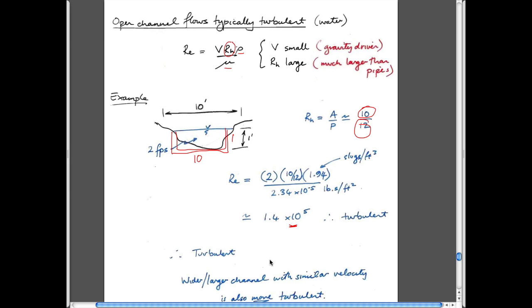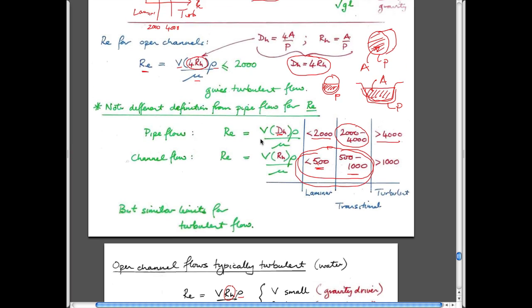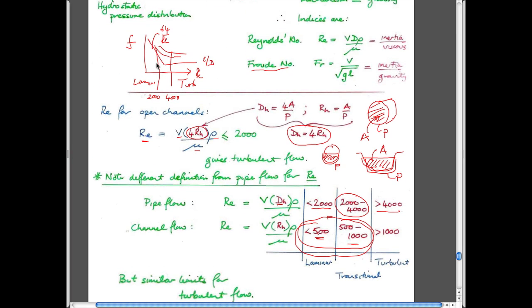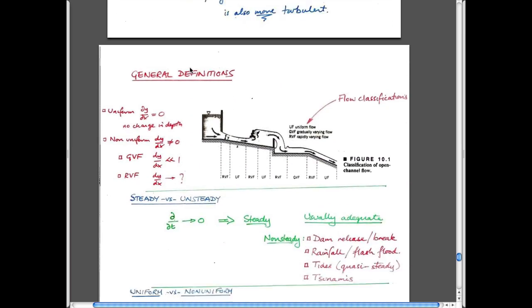And so all the cases that we'll look at are for magnitudes of behavior where the flow is turbulent. So we don't really have to worry about cases with magnitudes less than this, where we'd have to worry about friction factors being a function of Reynolds number. We'd expect that the friction factors we use to define the drag on the flow will all be constant, and they won't change with the flow velocity. So that's one simplification that comes out of our view of this.